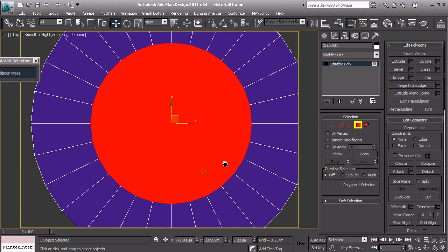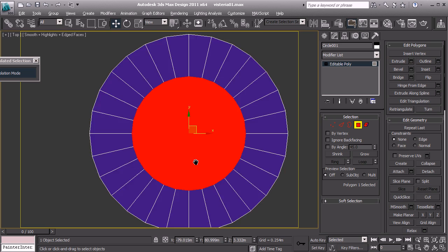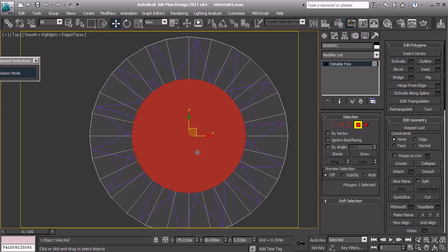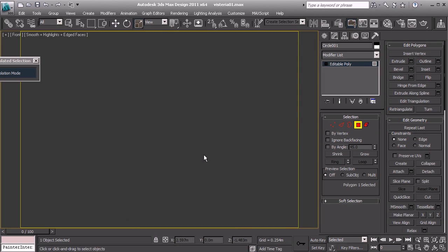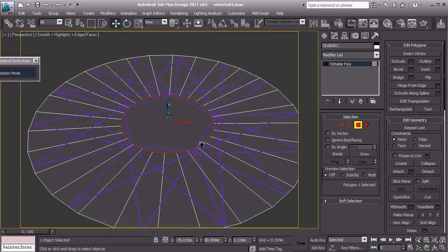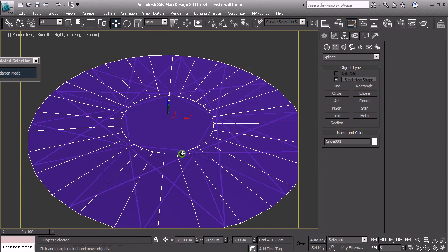I will go to the top view, enable Alt X to see through the element, press F2 to disable the polygon view, and we'll rescale a bit the center polygon. And right now I will move it down to fit the cables, and our distribution object has just been created.